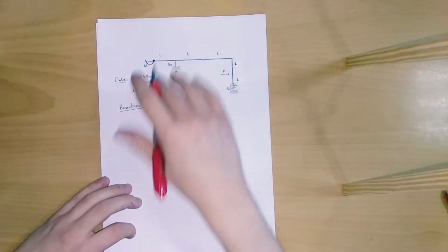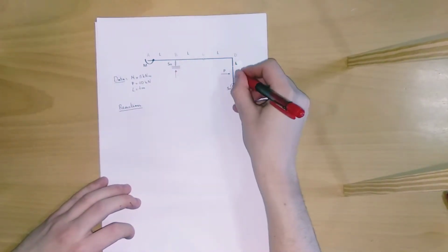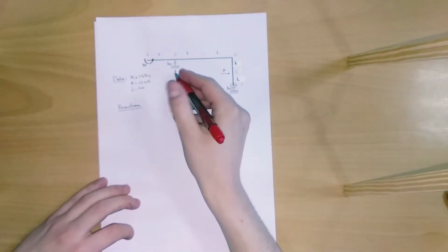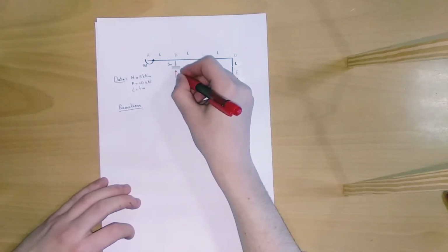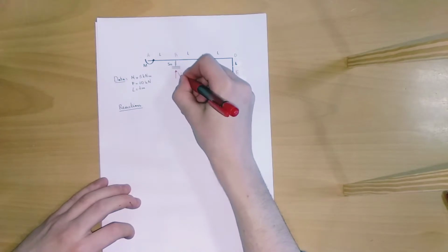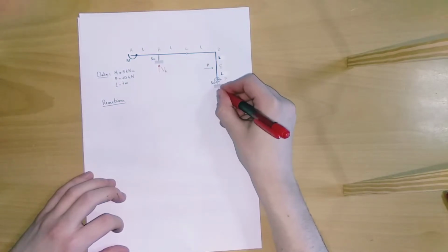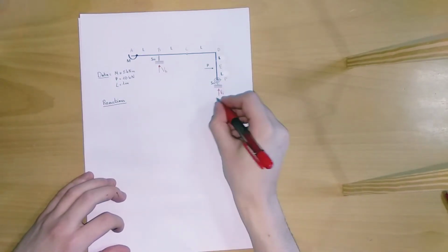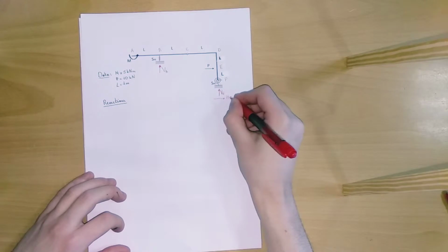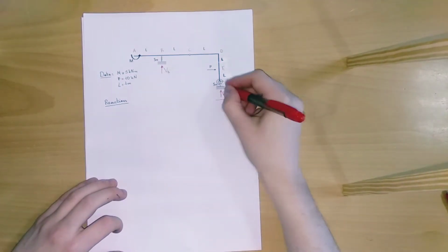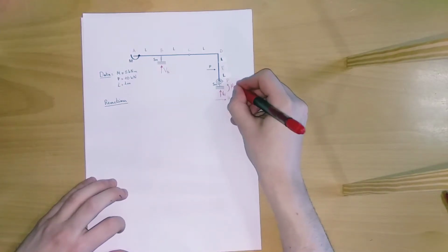I'm going to start calling the different points A, B, C, D, E, and F. So here, in this support, we're going to have a vertical reaction, which is going to be called B. Well, we go to the other support, we're going to have a vertical as well as a horizontal reaction, and the effect of this circular spring is going to give us also a moment reaction called MF.